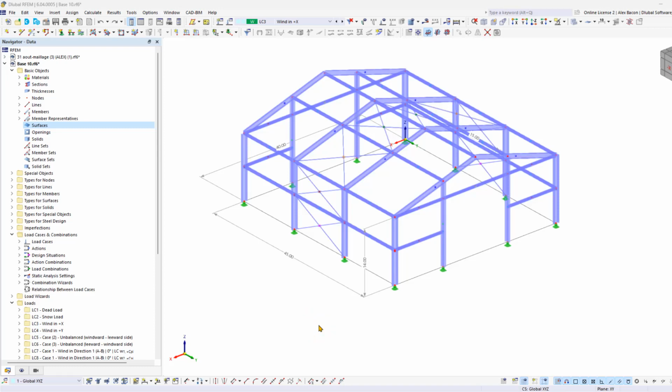This marks the final chapter of the steel hull loading tutorial. In this video, we will demonstrate how to create horizontal wind loads using load transfer surfaces. Before we apply the horizontal loads, we must create the lines to close the open cells, such as the gable of the hull.